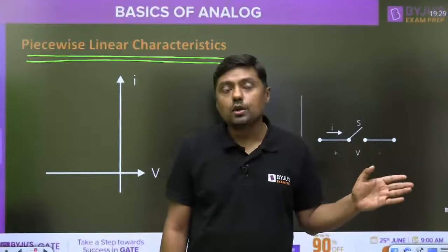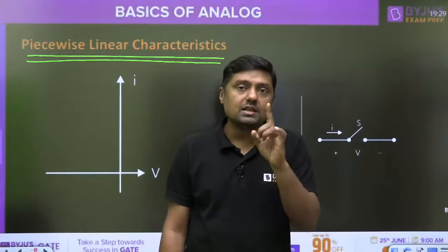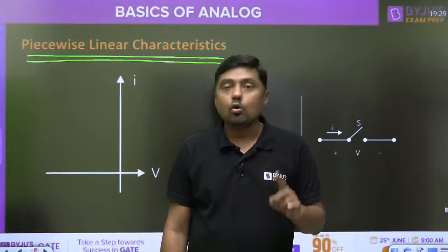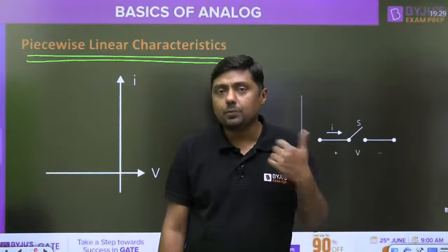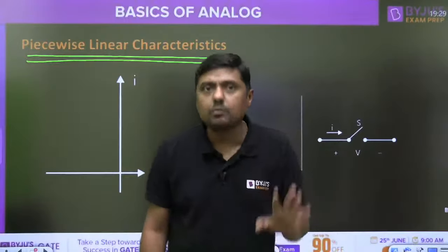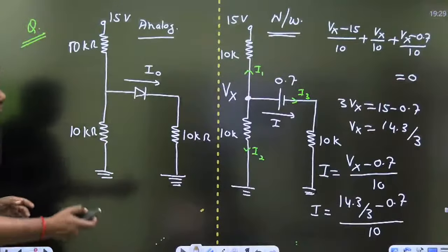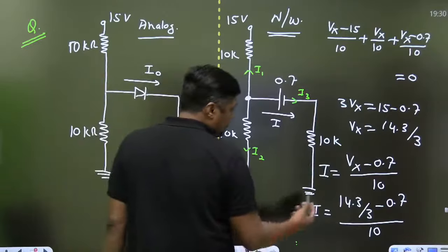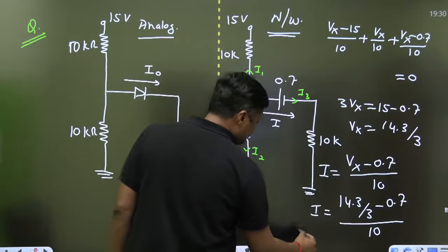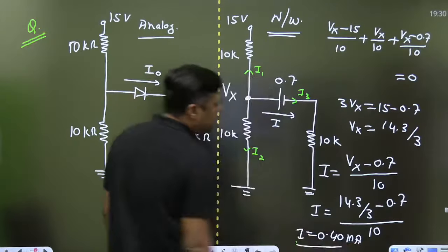Resistance is in kilo ohm, so the current will be in milliampere. And the second important thing, it will be less than 0.5 milliampere. Why? Because under ideal conditions, we get 0.5 milliampere. Then under practical conditions, definitely the current will be less, because this voltage will oppose. And that's why, if you are getting 0.4 something, that is your correct answer. You can check. 0.40 something milliampere.